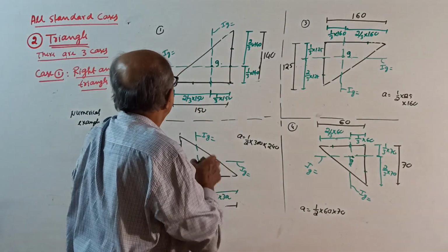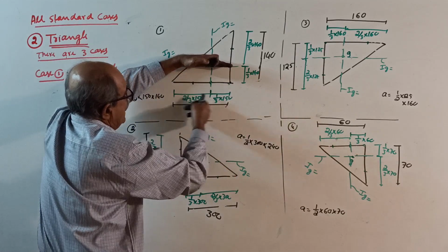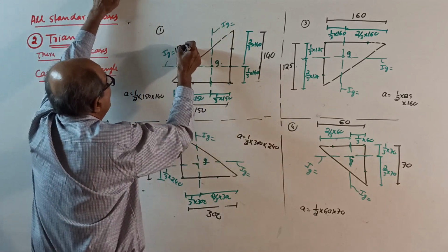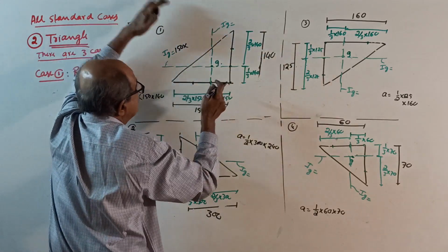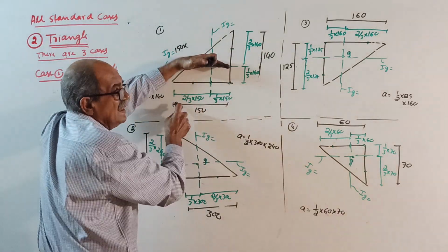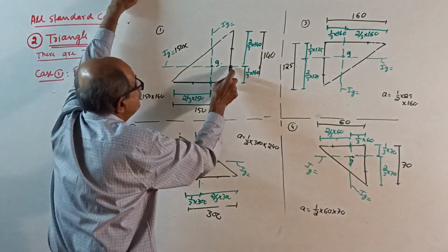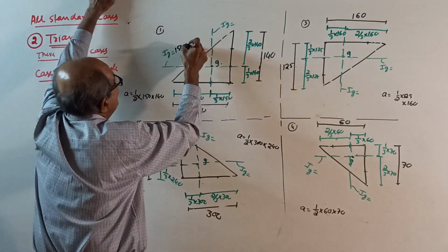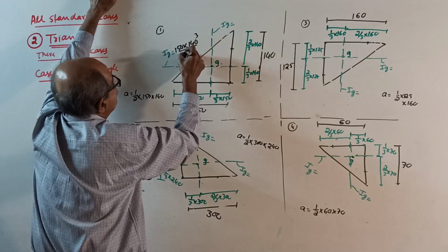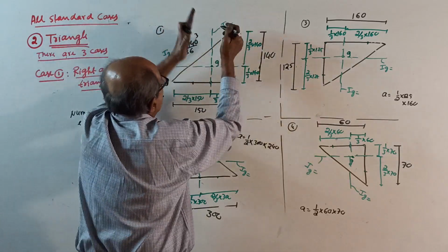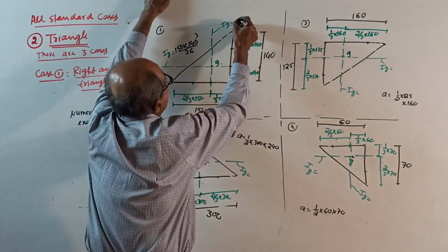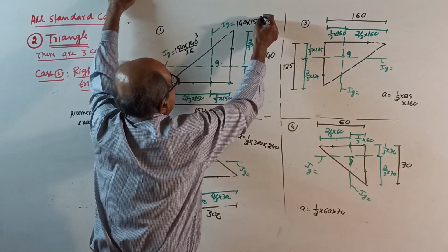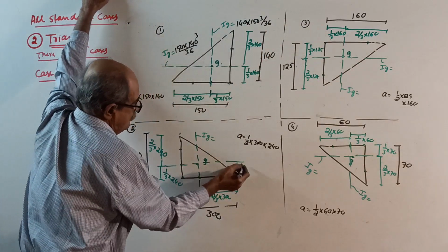Writing not proper. Start. This IG, parallel is 150, that's all. Then the other one is 140. First decide the parallel. Write parallel as it is, the easiest way. Which is parallel to the axis, write as it is. Which is the other one, perpendicular, cube it: 140 cube divided by 36. For this IG, parallel 140, into perpendicular 150: 150 cube by 36.